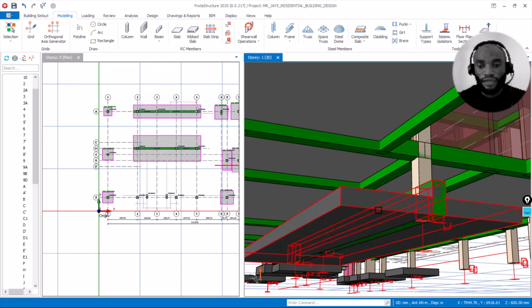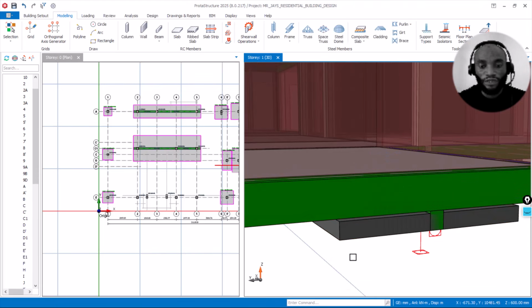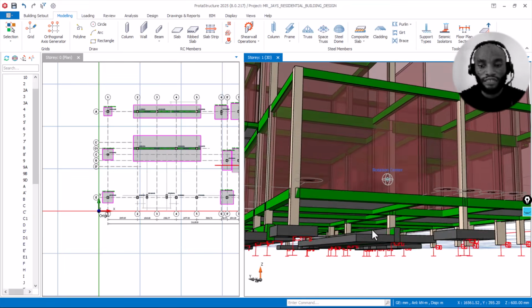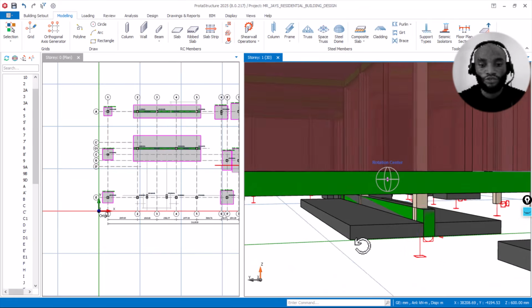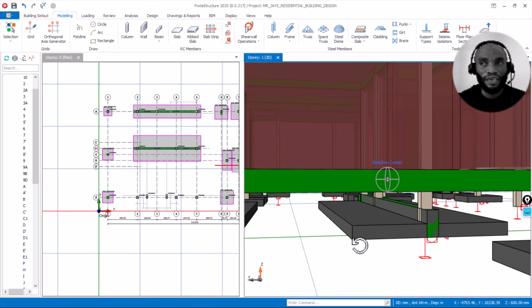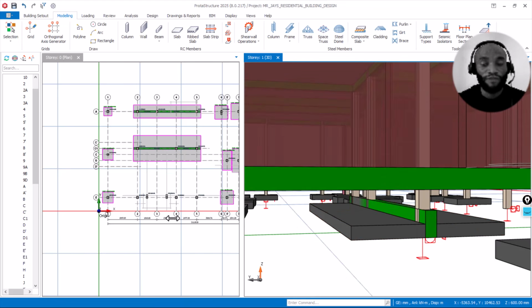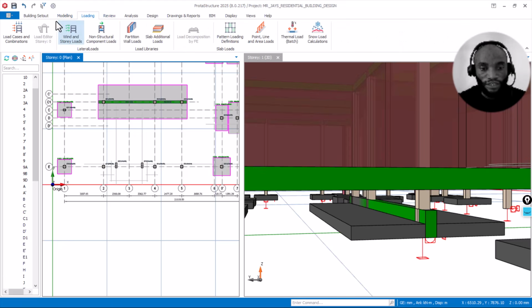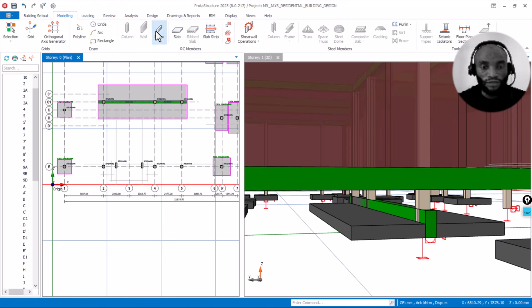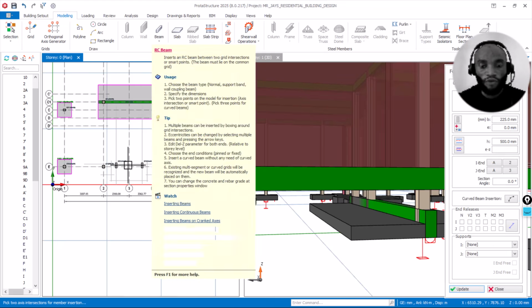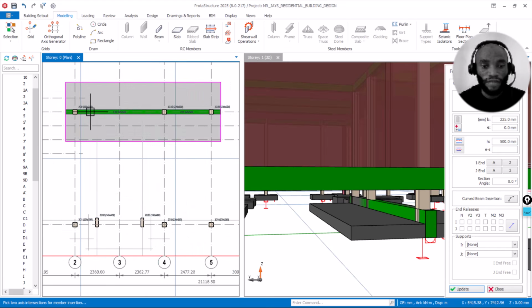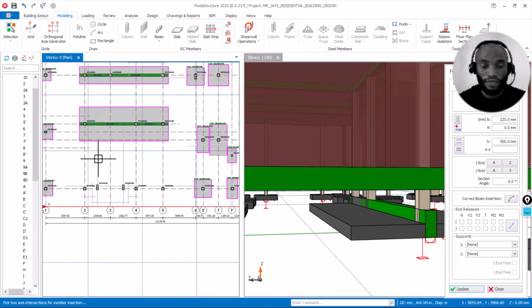Although most times when you're getting a bigger footing, it means a strip footing can no longer work, so you can switch to a mini beam raft. That is fine, but this is just for the sake of this video. So this is how to design a strip footing, or if you're combining two different types of foundation. This is okay because you have only 1.5 here, 1.5 here. It's not bad.